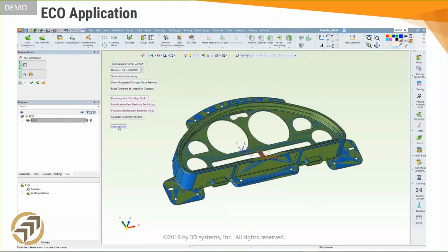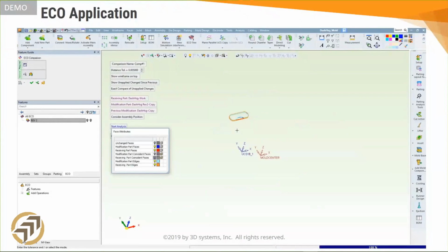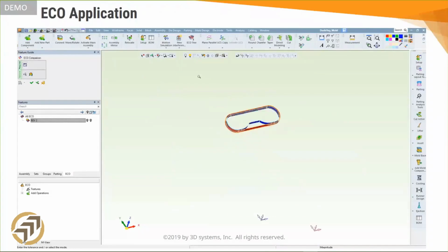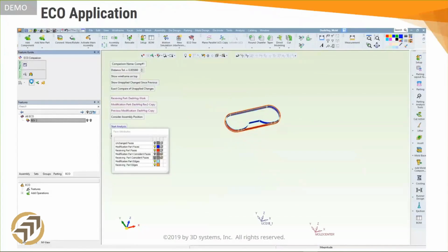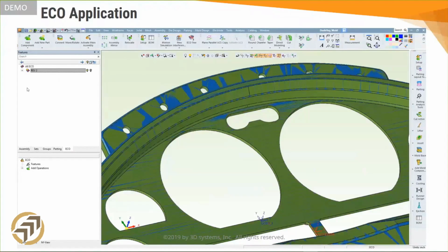An extra bonus at this step is the ability to add a third part to the comparison, the one you added any draft or molding features to. This filters the comparison result even further, keeping your part preparation work safe from replacement.